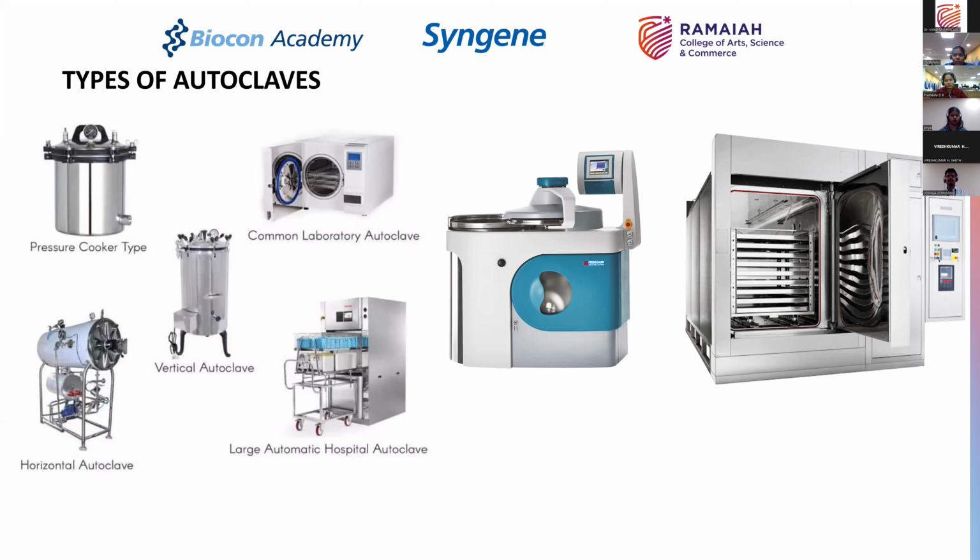In sterile manufacturing operations, however, we are only going to use what is called pure steam. So we did study about pure steam or the different types of waters that we use in the pharmaceutical industry. So a steam which is generated using purified water, which on condensation is going to be free of endotoxin, free of any gases, and is meeting the quality of water as specified by US Pharmacopoeia section 41, is what you will use in modern sterile manufacturing operations.